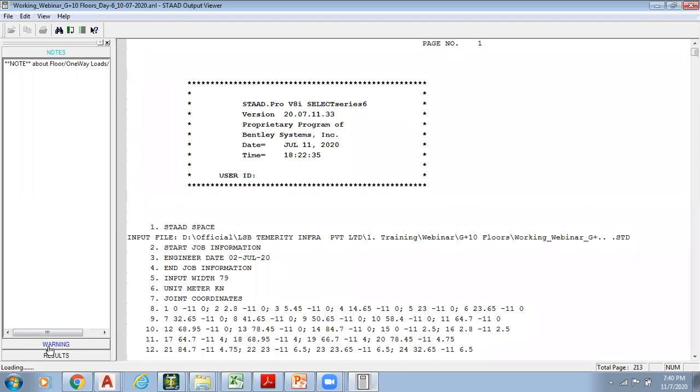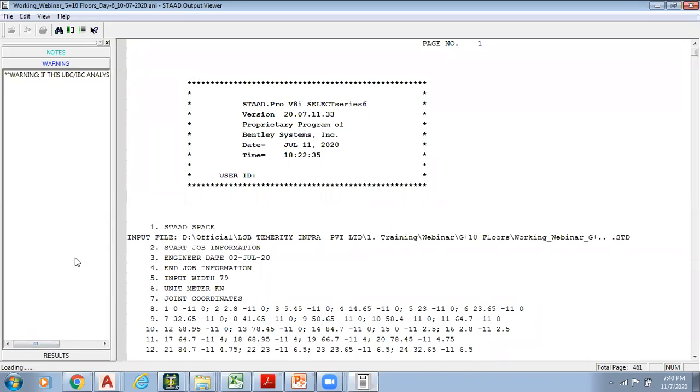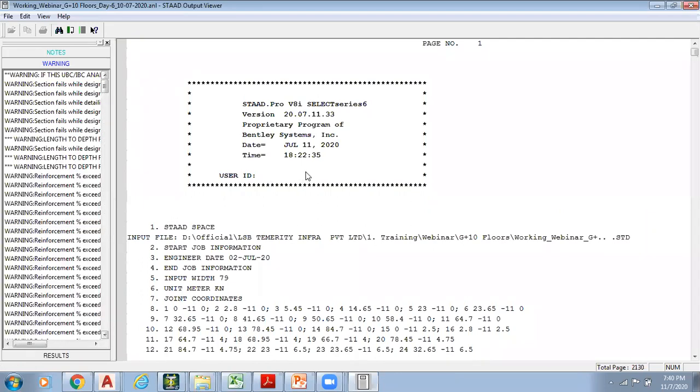And of course, fortunately, we were not having any kind of errors, but we had warnings. So we went through all this type of warnings, and there are four types of warnings available in this STAAD output file. The first one, which is in fact not so much from a design point of view, is enhanced shear strength, which means when I have a member whose length to depth ratio is less than or equal to 2.5 times. Usually that definition is applicable only for the deep beam cases.